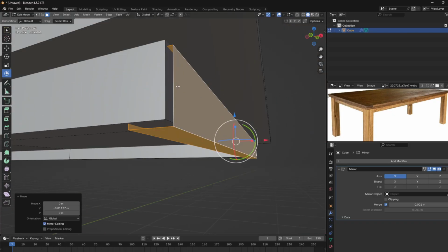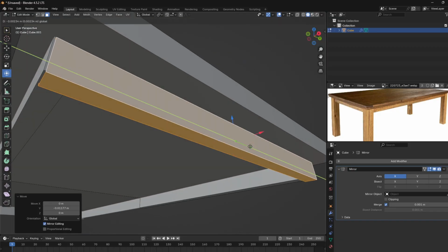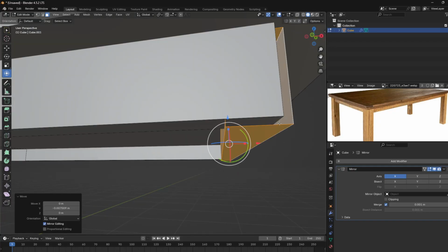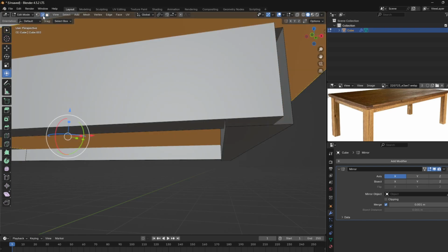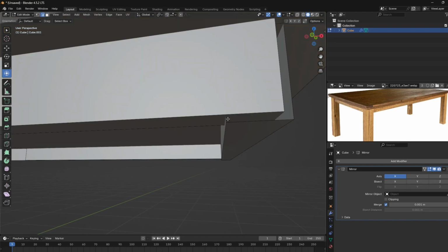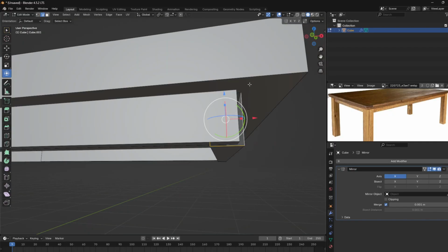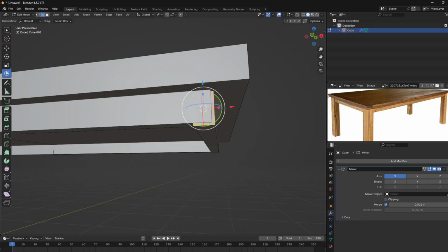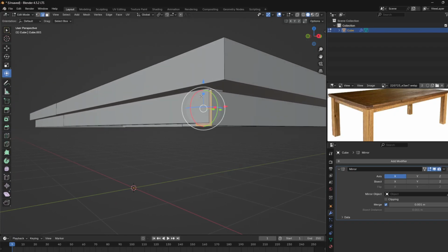I can see that there's a hole here. We can always fill holes. So for example, I want this place to have a face. All I need to do is to switch to edge mode, then select these edges. So I've hit shift, then I'm clicking around the edges like that, then I can hit F. F stands for fill.